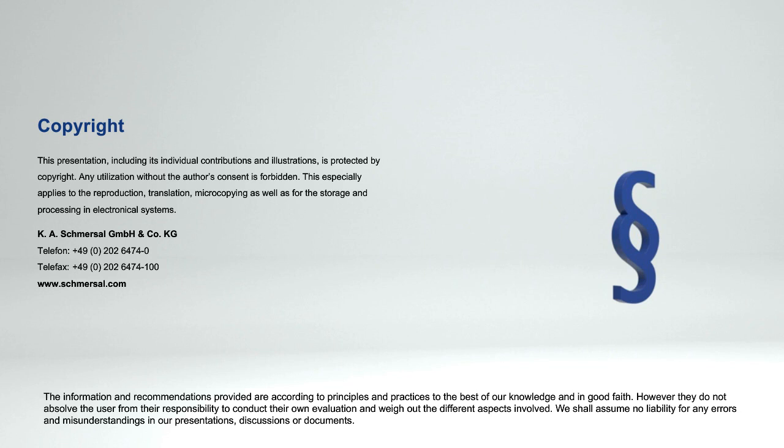So the control categories are specific design architectures, and you're going to see those referenced in other standards that say, you know, this minimum safety function in this particular industry needs to be a minimum category 3 PLD. Especially if you look at individual components from a manufacturer, you may look up the component and the standards they apply to, and they may say up to control category 3, up to performance level D, per ISO 13849. So the main area where you find that information is ISO 13849 Part 1, where they describe control categories, but they originally came from EN 954.